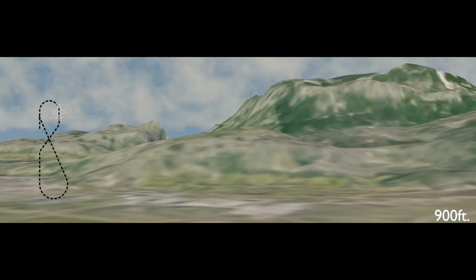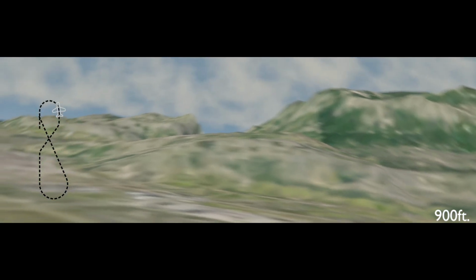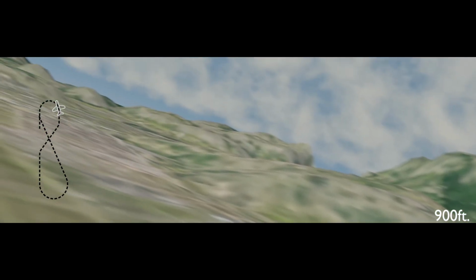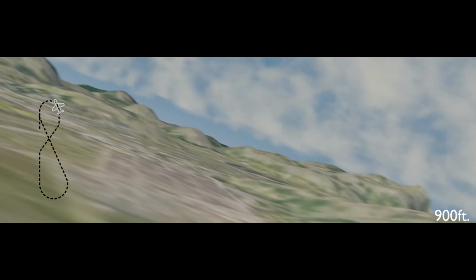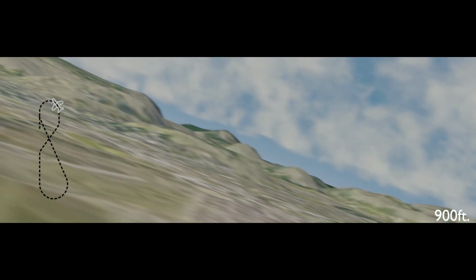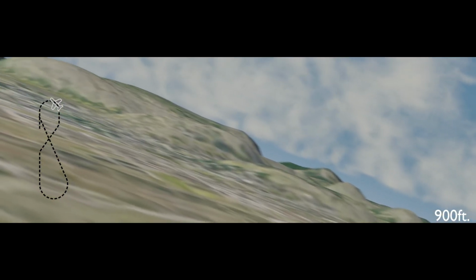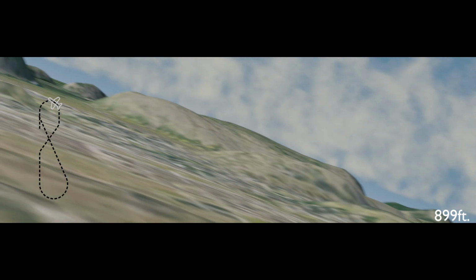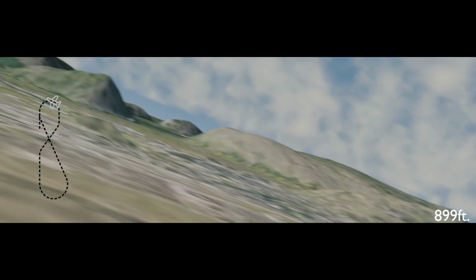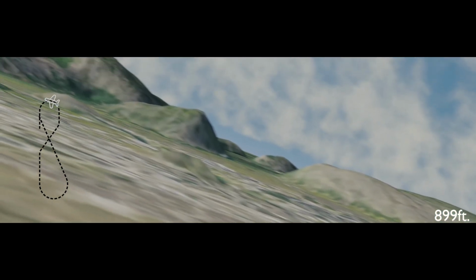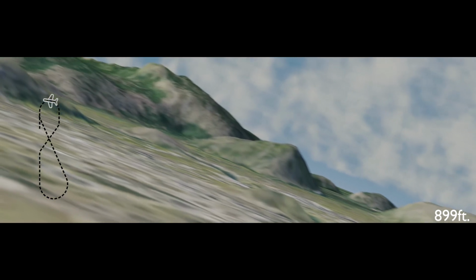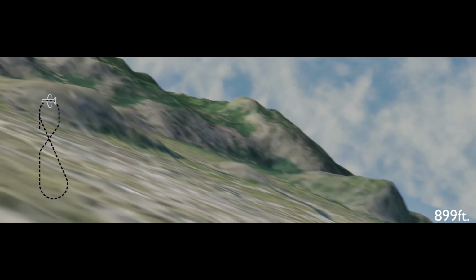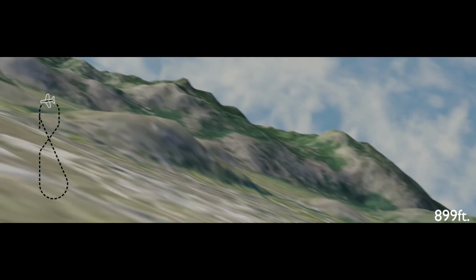Approaching the base turn, we establish landing configuration and reduce to final approach speed, which in this example is 130 knots. We have visual reference with the ground for this manoeuvre, so to satisfy the stabilized approach criteria, we need to ensure that we're fully configured with the correct rate of descent, power and trim set by 500 feet above the runway at an altitude of 620 feet.